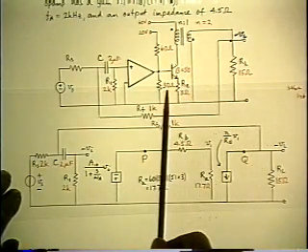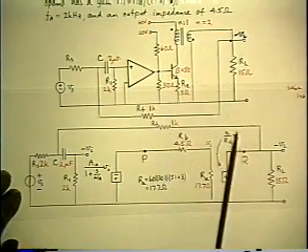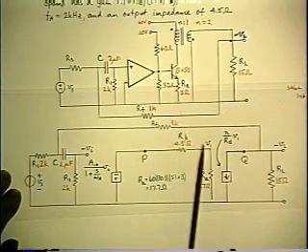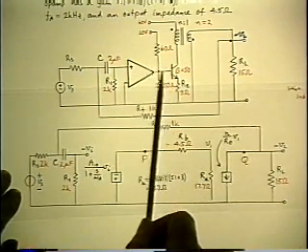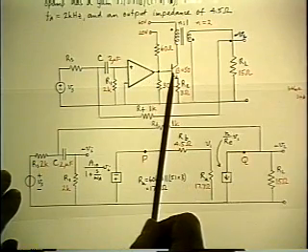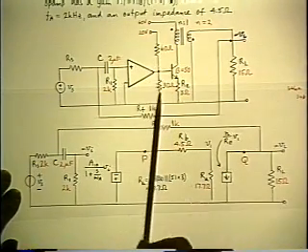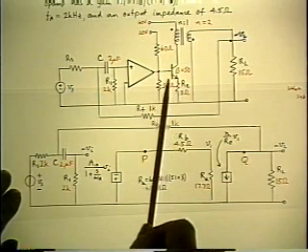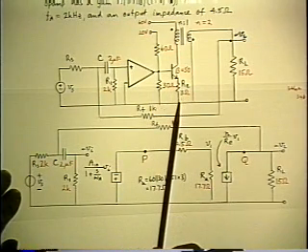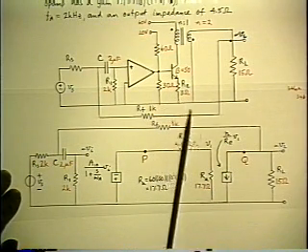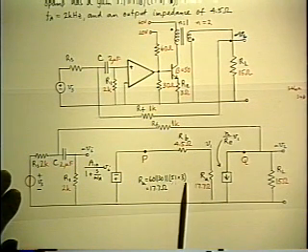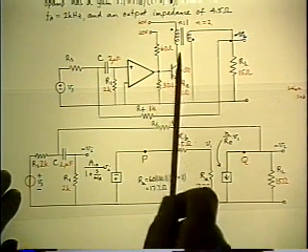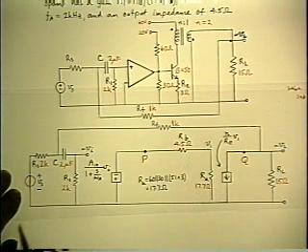First, the power stage. Starting from the voltage V1 on the base of the power stage, it's going to show up across some equivalent input resistance to the power stage, which is going to be 60 ohms in parallel with 30 ohms in parallel with the reflected RE. That is 60 parallel 30 parallel 51 times 3, assuming a beta of 50 for the power transistor.